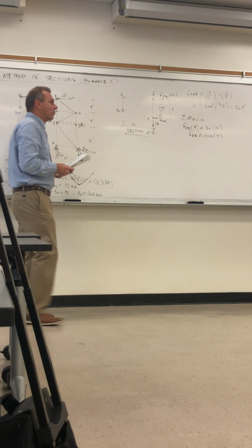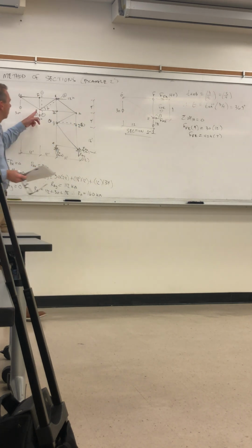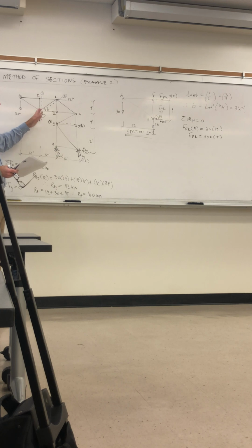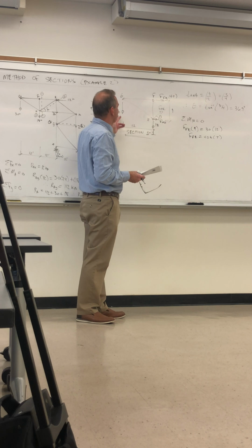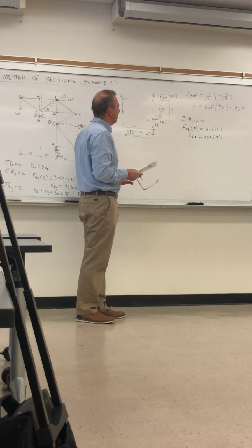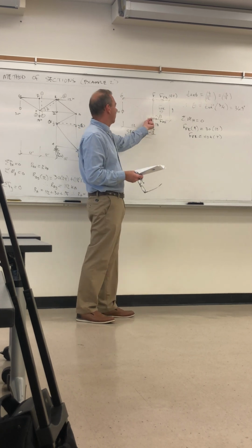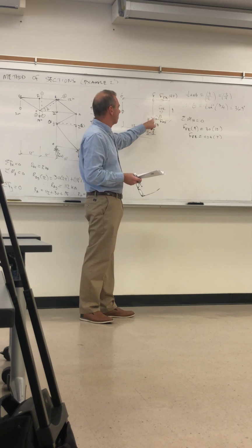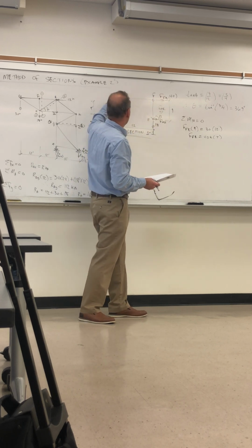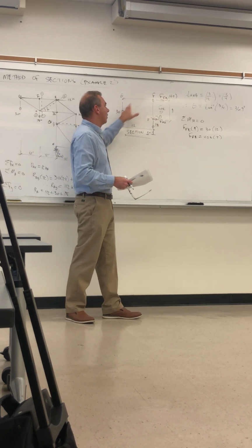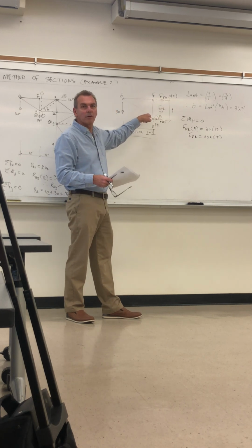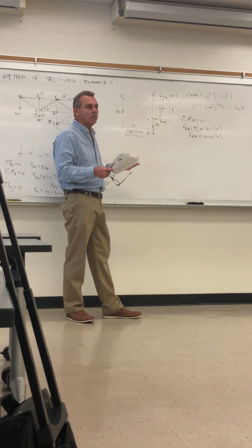So you can see this type of a problem, it's very easy to have everything kind of coming together at a point like that. We can take a cut here and then solve for F of FE. Right? There was only one other force that was providing positive moment. And so stepping back a little and just looking at it, you can see it's a balancing point, right? There's a moment from this, and this force times this is balanced by that force times this, right? The moment that way and the moment that way, about that point. Only those two things are contributing. So they're in balance.